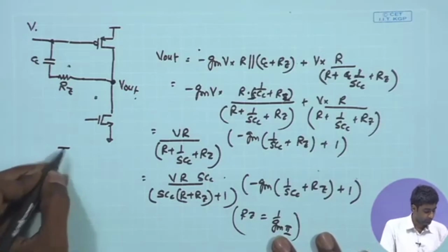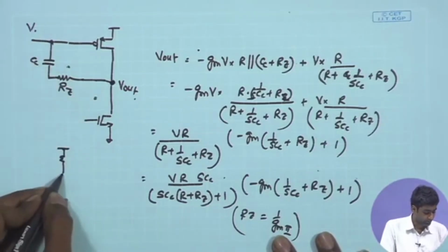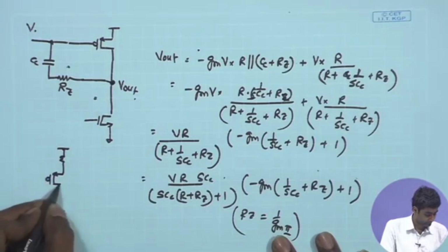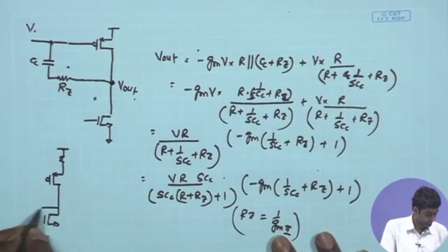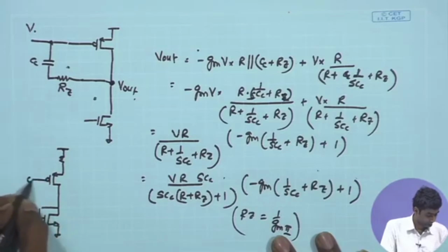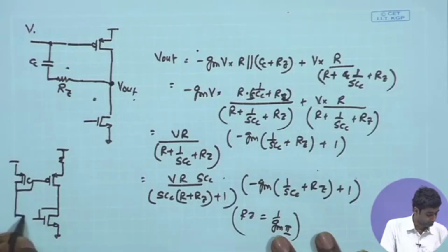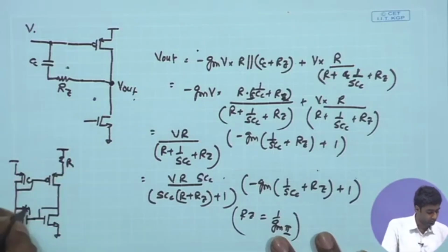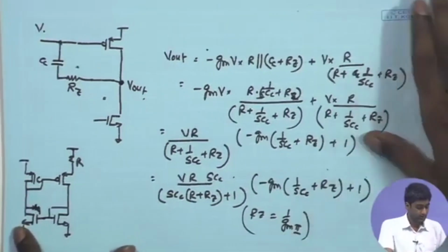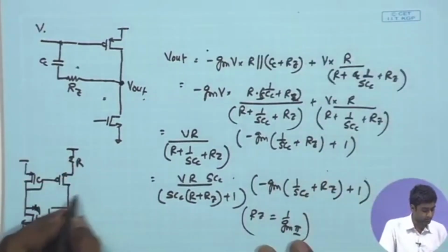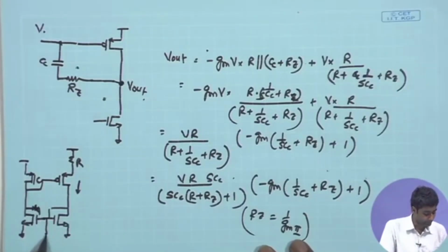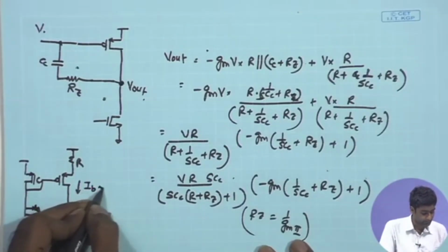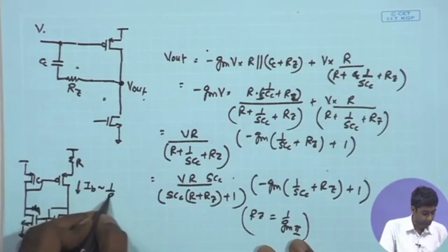can use a PMOS current reference. We will be looking into this circuit in a little bit more detail, and in this particular circuit, if this is an R value which is being used, this is not a connection. So, in this particular circuit, if this is the R value, we can show that the biasing current that we get out of this I bias is proportional to 1 upon R square.